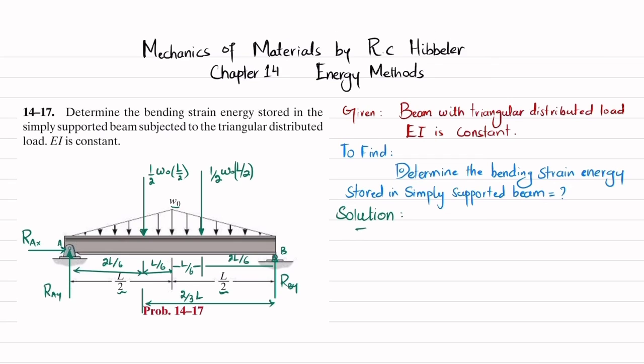So which equation of equilibrium are we applying? That sum of all moments about point B is equal to 0, taking the counterclockwise moment as positive. So about point B, the first moment will be due to this RAY and the perpendicular distance is L, and this is producing clockwise moment, so it will be negative. So I will write minus RAY into perpendicular distance L.